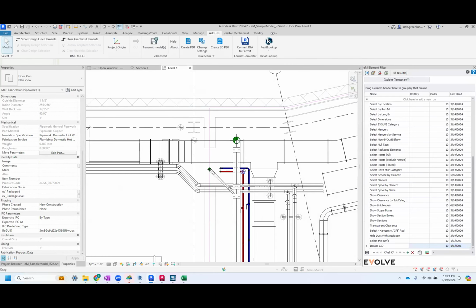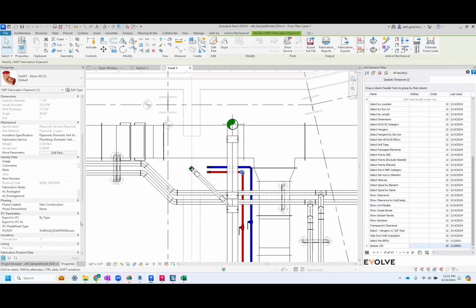Now, a service abbreviation, you may not know it offhand, but you can look at your parameters here. We have service abbreviation HW, or let's see here, we have CHWS. So now when I run this rule, it's going to prompt me for the CID. I'll do 2523. Okay. Now, what's the service abbreviation?